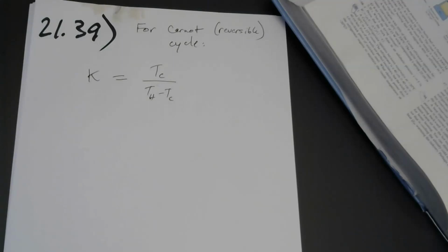Again, I'm just pulling this ratio out of thin air, but suppose that on a hot day when your kitchen is really warm, you have to spend $1 to scoop out 1 megajoule of heat from your freezer. On a cold day when your kitchen air temperature is closer to the desired temperature inside your freezer, you may only have to spend 60 cents to scoop out that same 1 megajoule. So it takes less work input per megajoule of heat when the temperature difference is smaller. And maybe that's not intuitive. I don't think it's really intuitive for me.